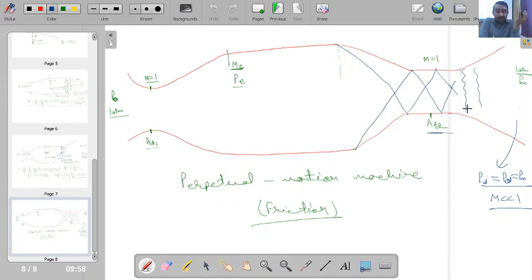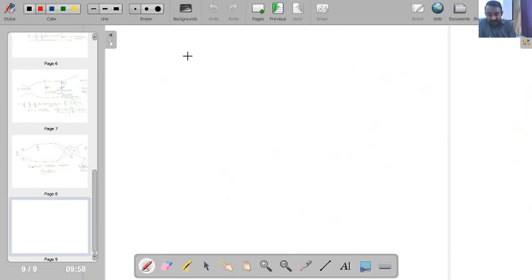So this is the need for a diffuser, that it decreases the requirement of pressure to maintain supersonic flow. But another important aspect is that when we are using the diffuser, we must also quantify the efficiency of the diffuser. For using a diffuser and defining its efficiency, a number of parameters are used, but one important aspect is that the combination of a normal shock wave and then a diverging duct is considered as an ideal diffuser combination.